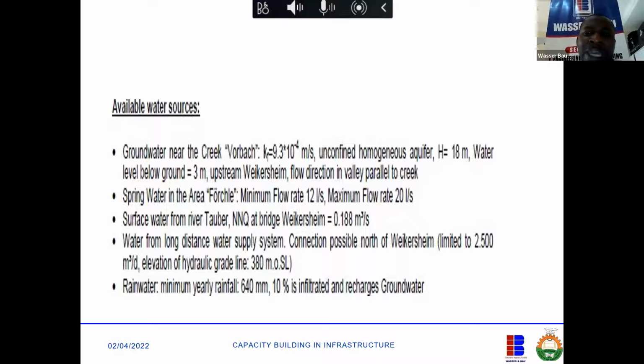If the water is full of iron 2, the first thing you do is to aerate it. Bring in air, bring in oxygen. Oxygen is already 21% of air, okay? So you bring in air, the air will react with that iron 2 inside the water and make it insoluble, thereby converting it from iron 2 to iron 3. Iron 3 is insoluble, in fact, it's partially soluble.